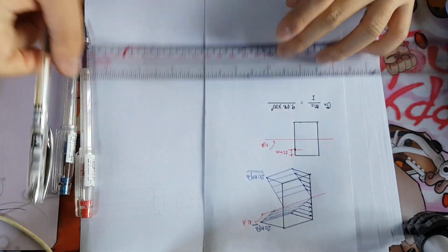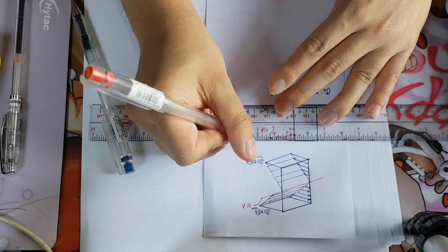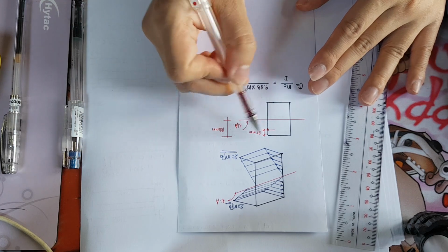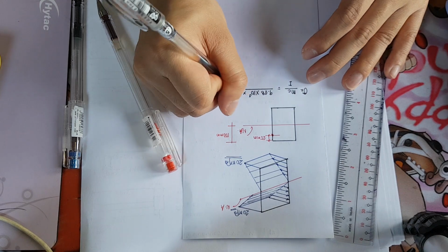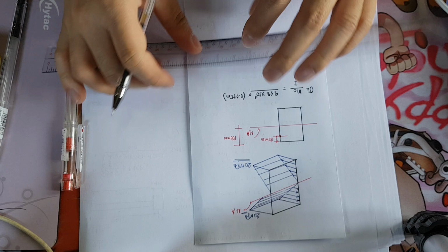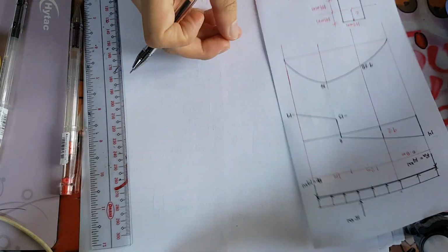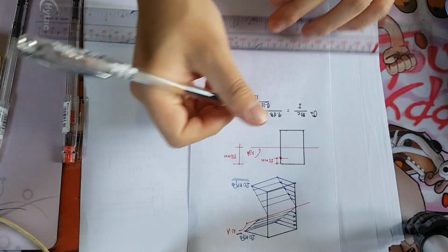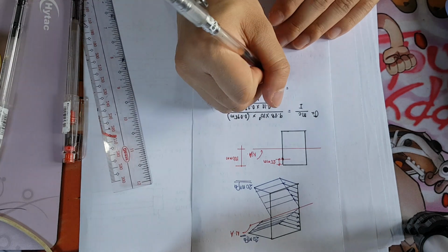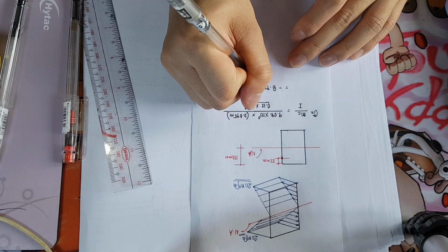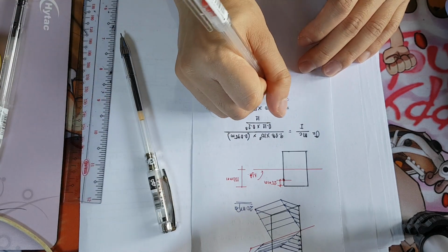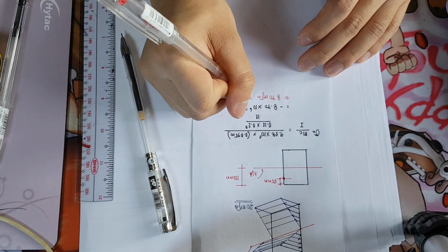So what is our value of c? So we have here the distance from the farthest fiber to our neutral axis to be 100 mm. So we subtract 25 mm from 100 mm, and that is 0.075 meters divided by the moment of inertia. Did our moment of inertia change? No. It is still 0.12 times 0.2 cubed over 12. Therefore, our stress is equivalent to negative 8.70 times 10 raised to 6 pascals, or that is equivalent to 8.70 megapascals, and it is in compression.